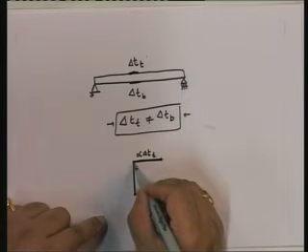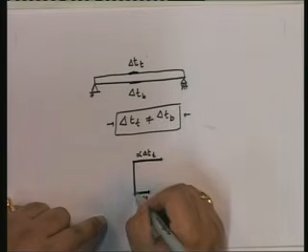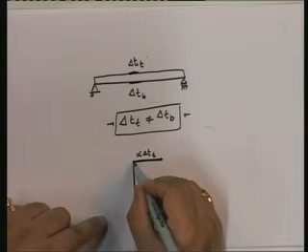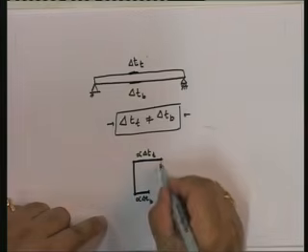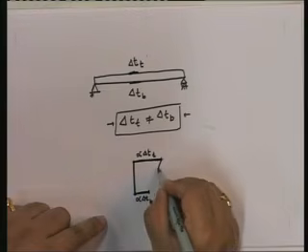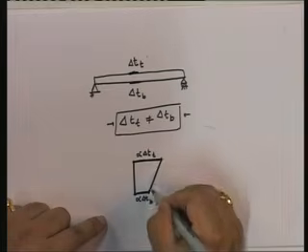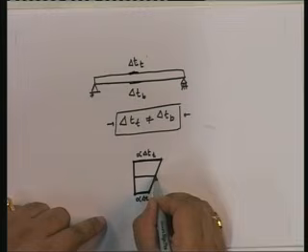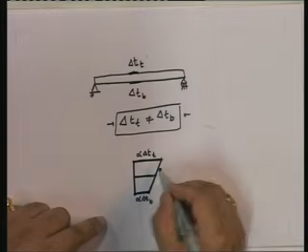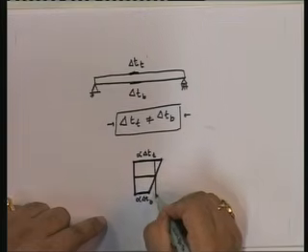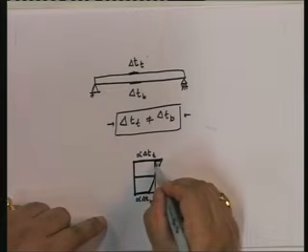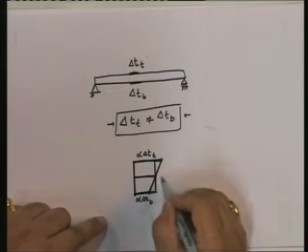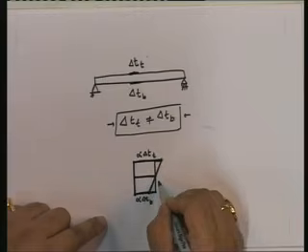And as long as the temperature gradient is uniform, in other words, it is linear from the top to the bottom, you will see that each one will deform separately, and what you ultimately have is not only that the neutral axis has gone in this fashion, but if you look at the section, it has actually rotated. Rotated means there is a flexure.